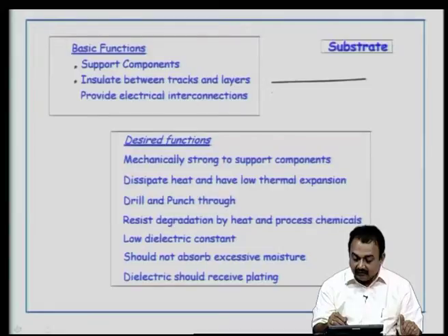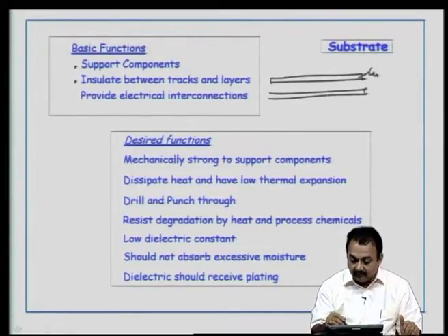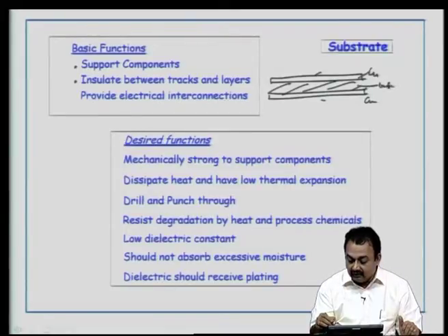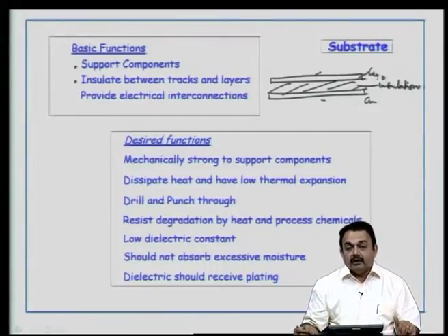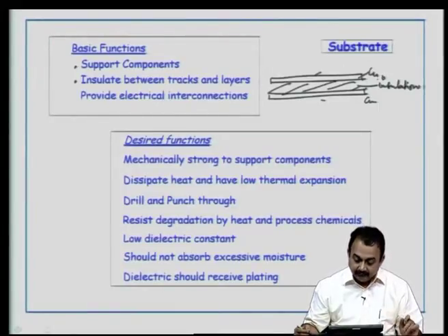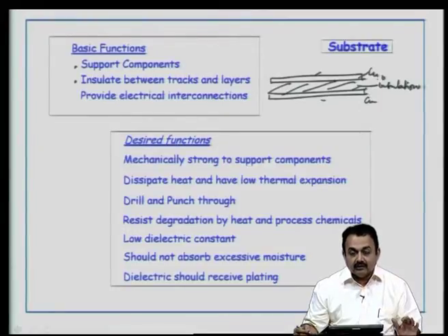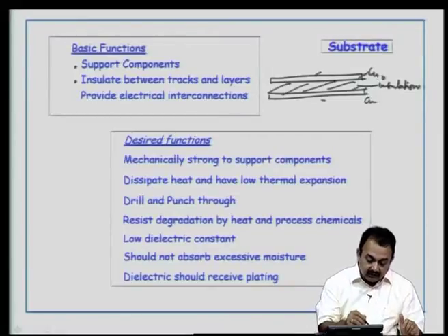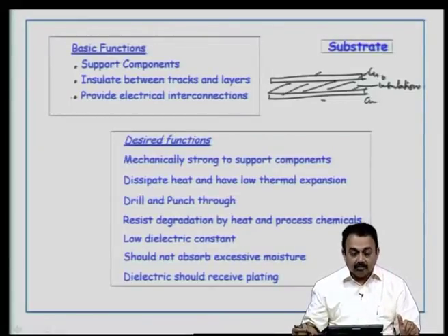Imagine a dielectric material and then you have copper here and then you have the copper here at the bottom. So, if you run tracks on top and bottom, this provides the insulation, and it also enables a very good electrical performance for your system by minimizing crosstalk and other electrical parasitics.